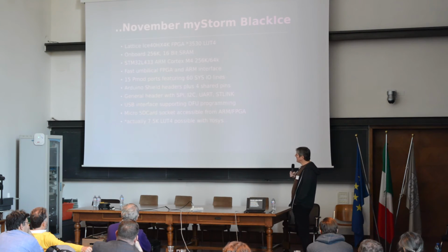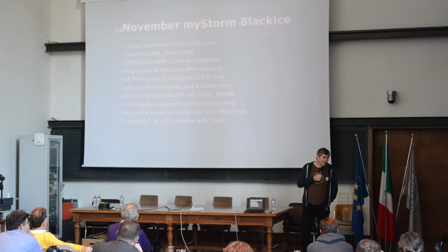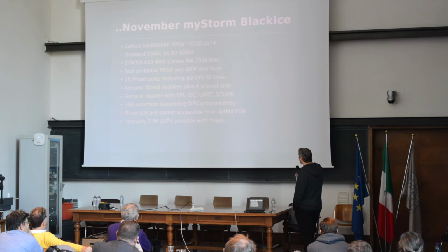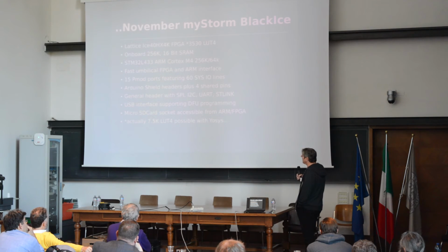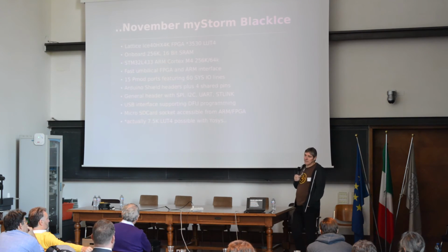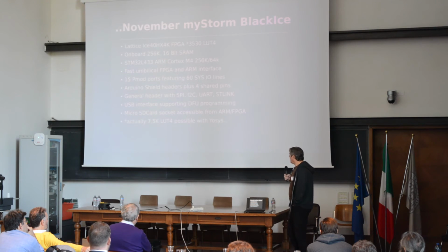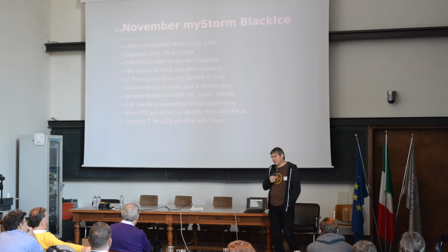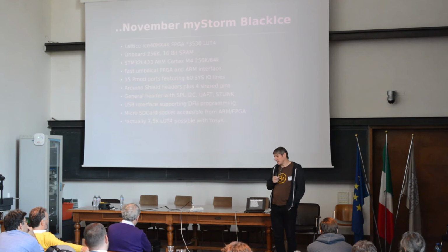Again, we have the USB interface supporting DFU programming. We have added, or I'm actually in the process of getting this operational at the moment, we've added a micro SD card socket. This is accessible from both the ARM and the FPGA. This is useful for storing multiple images, for example.